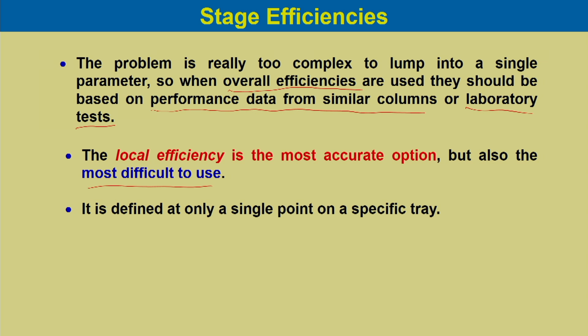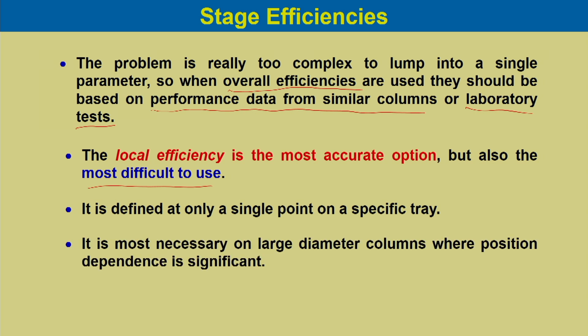This is important when we have a large diameter column, where the tray area is much bigger, and the efficiency of the tray depends on the geometry of the column or the geometry of the tray. So, it is most necessary on large diameter columns where position dependency is significant.